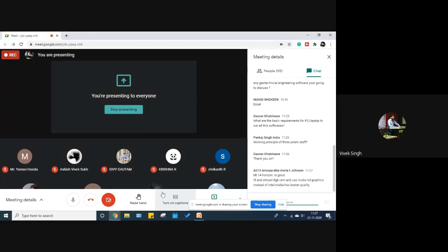So you have two options there. One is the prism, and the other is the sticker. If you want accurate measurements, you use prism. Otherwise, sticker is also a good alternative. At construction sites, we actually prefer sticker because it's handy, it's small, and you can use it very easily. It's easier to hold. In case of prism, you need a staff itself, and you have to place that staff at the point where you want to measure that coordinate or the distance.